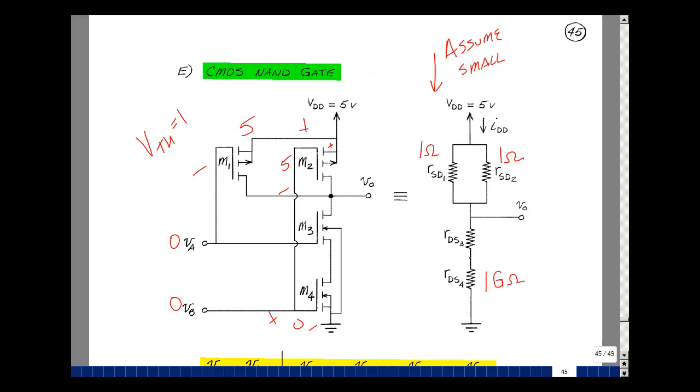What's the voltage here? If I can find this voltage, I can find the gate to source voltage at transistor 3. I've got a small current flowing, and I've got a big resistor here, so the drop across here can be anything, but I am limited to a 5 volt power supply. So this node voltage here, I'll call it V sub x, is somewhere between 0 and 5 volts. If this voltage is 0, and this voltage here is, say, 5 volts, it's a minus 5 for the gate source voltage. If this was 4 volts, I'd get a minus 4. If it was 0, I'd get 0.